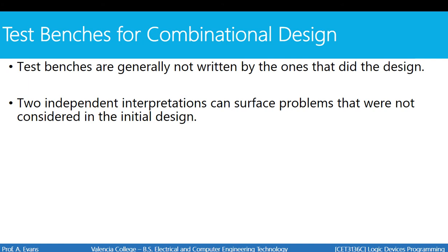The testing team had no hand in actually writing the code for a particular design or a component. Their job is to try to break your code as a designer. So if you're a test and verification engineer, you would be the person who looks at the specification for a half adder. You would say, oh, okay, it has to have 2 inputs, it has to have 2 outputs, and the outputs are going to be according to this truth table for a half adder.